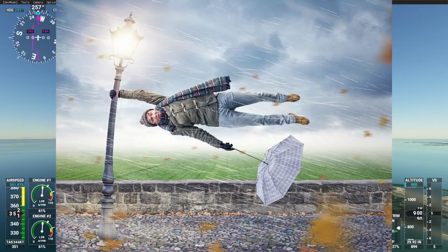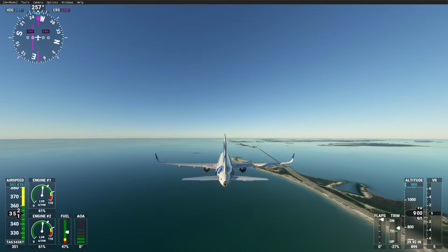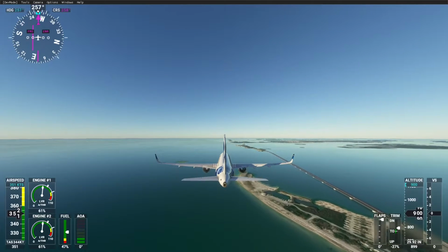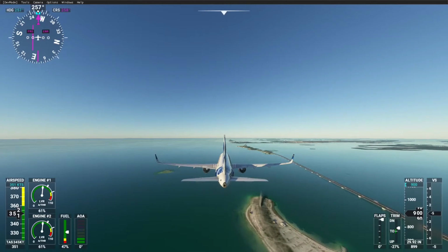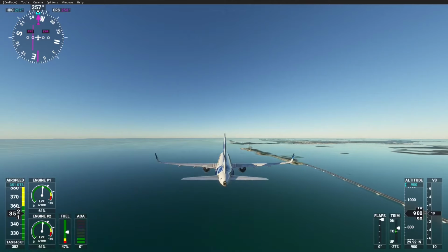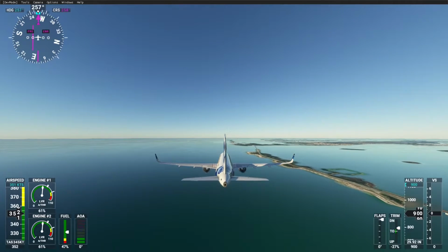When the ram air push button is pressed, the outflow valve will also open 50%. This provides a through flow, so if you can imagine, it's like opening two ends of a Pringles can, and the air is just going to flow through it. But the outflow valve is only going to open provided that your delta P, so that you haven't actually pressurized the cabin. So you're going to have to get it down, depressurize the cabin, and then push the ram air push button to get maximum smoke clearing effect. This is achieved via the checklists.